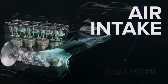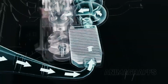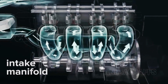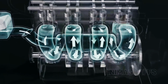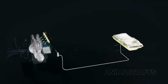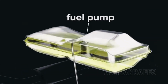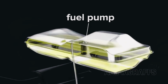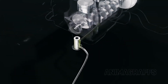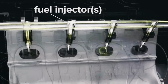Air intake. Air comes in through the air filter, and then into the intake manifold, where it mixes with fuel before being sucked into individual cylinders through intake ports. The fuel pump carries gas from the tank through a fuel filter to the engine, where fuel injectors emit a precisely timed spray of gas into the intake port.